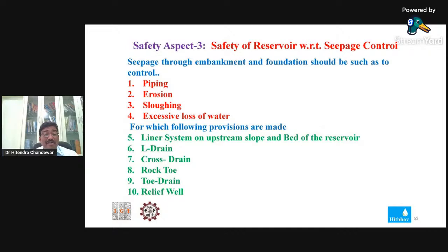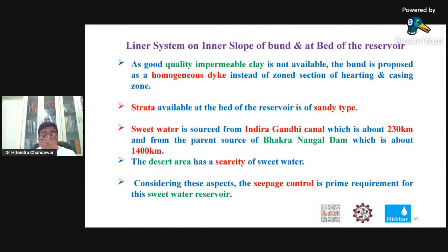Liner system we have provided on the water side, then lateral drains within the earthen body, then cross drains were provided within the earthen body, then a toe drain was provided at the outer toe of this earthen embankment, then toe drains were provided along the periphery of this reservoir, and we have provided one relief well. These relief wells help to monitor the health of the dam reservoir.